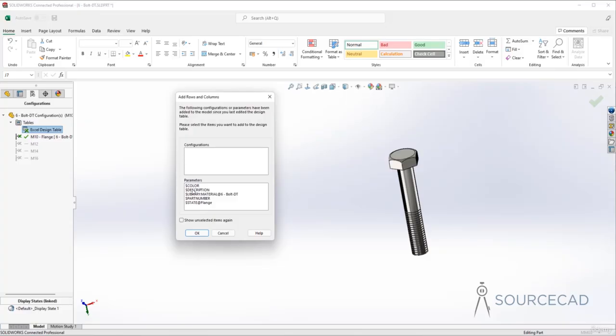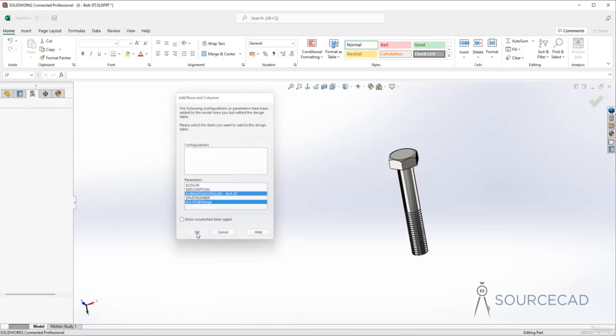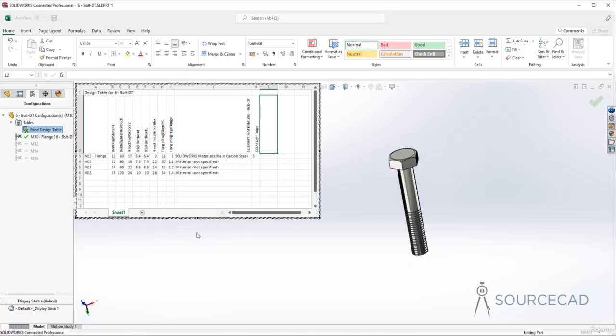Here we are, we've got these changes listed here. So there are several changes which SolidWorks recognizes here, and it will just list all the changes which it found, but we are interested in only two changes. The first one is this flange, which is its state, suppress or unsuppress state, and the second one is material. So we are going to just control select these two options, and with that I'll click OK.